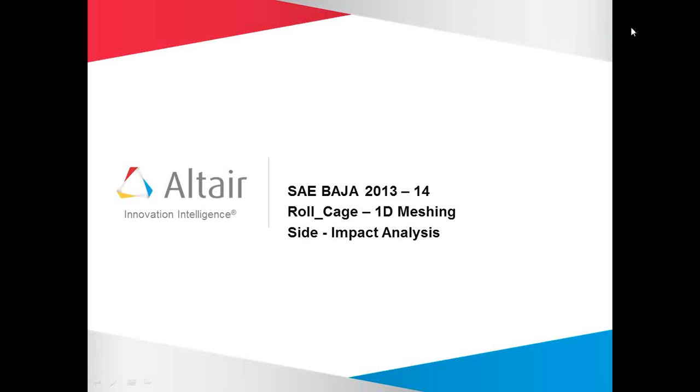In this video I am going to cover how to perform 1D meshing and side impact analysis. So I have a line CAD model in which the line geometry is there. Then I will show you how to create 1D meshing or 1D elements on this line data, roll case structure of line data. And then we will also see how to simulate side impact analysis using Radioss and Hypermesh. Then we post-process our result, that is we will view our results of displacement and stress and animation plot due to the side impact in Hyperview.